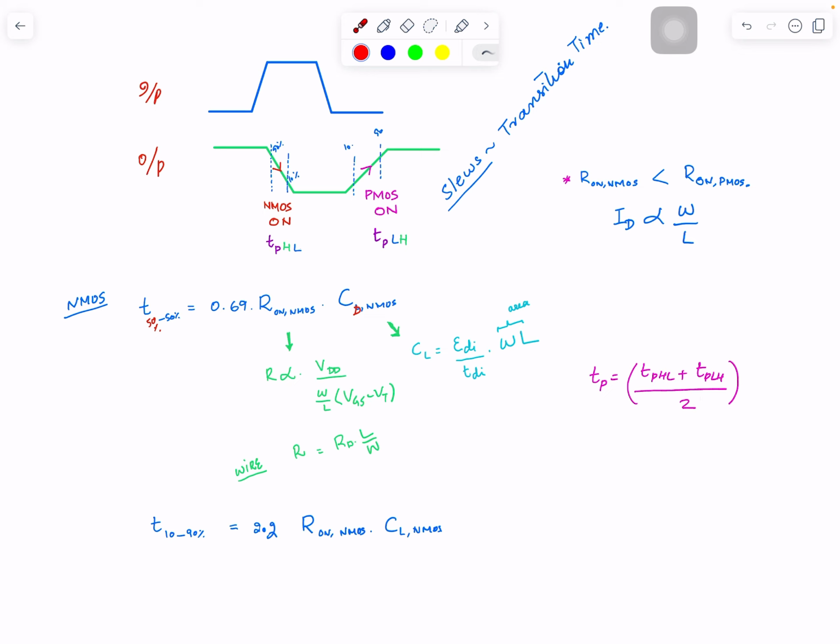But I think if you do it initially for hand calculation, that's okay. So now the second thing is, we covered the definition of transition time and delays. Now the question is, how can you reduce the delay and reduce the transition time? I mentioned in the last video too that you can do that by reducing R and C. But then the question is, how can I reduce R? As a designer, what things are in my control to reduce R and C?